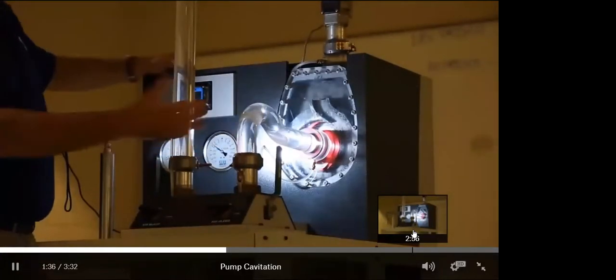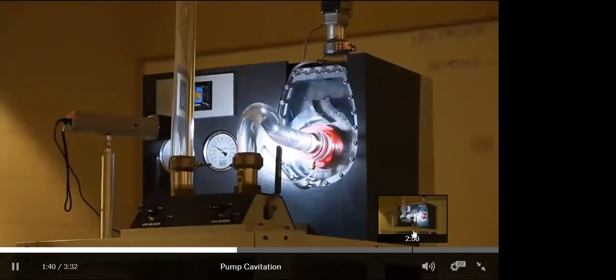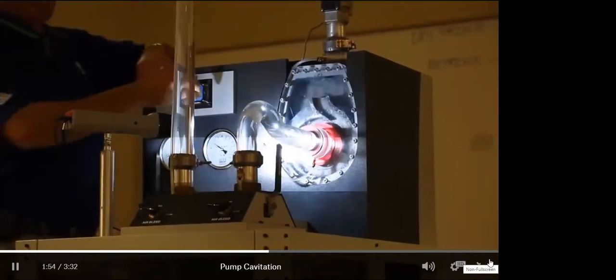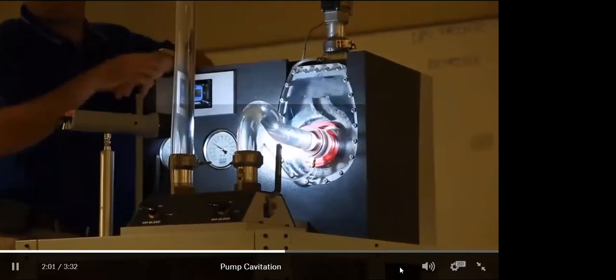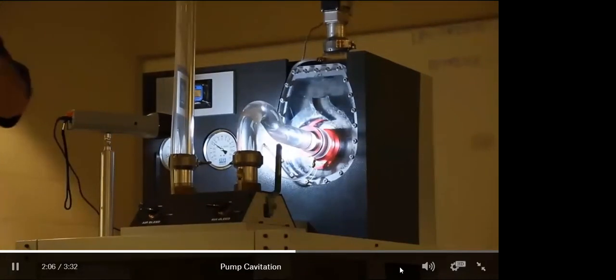I've got about 69, 70 gallons a minute going through a 1.25 inch opening. As I start to close that opening down real little, the liquid has to go faster and faster to get through that real small opening. Okay? So as the velocity of the liquid goes up, the pressure goes down. The liquid can't stay in a liquid state, it flashes to vapor. As I get to the eye of the impeller, on the discharge side of this pump, there's no restriction. So all that liquid slows back down and those vapor bubbles implode back into liquid.